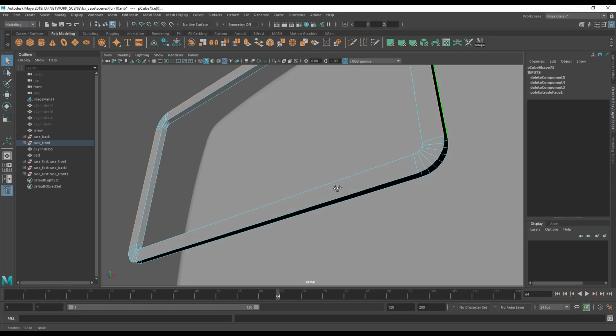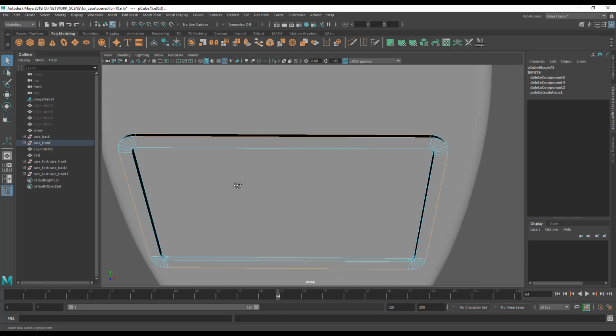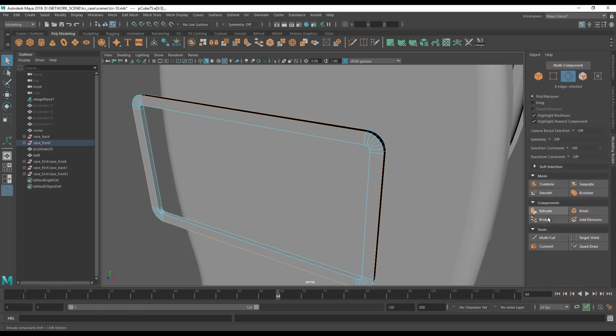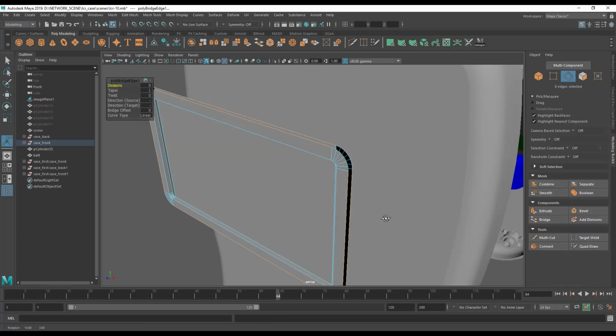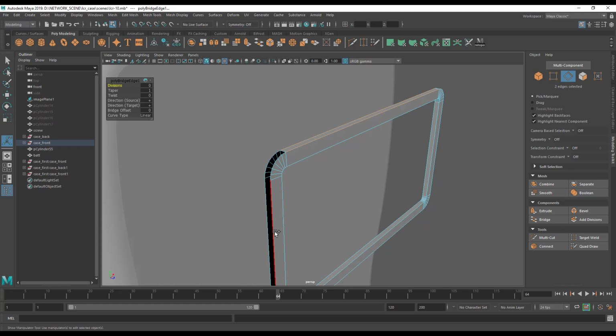Now in this particular instance it would have been quicker just to go into the front view, resize another box up, because you know essentially it's a box with a bevel corner. I'm going to do it this way just to show you can. Let's bridge this. Okay, that's not liking that bridging all at once, so let's just bridge it individually.